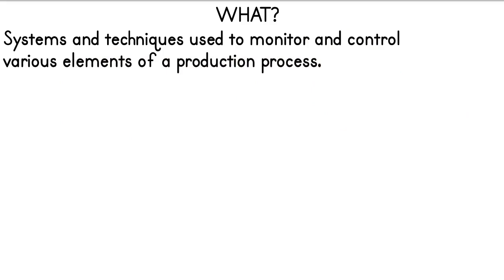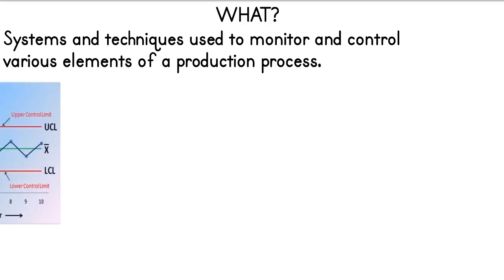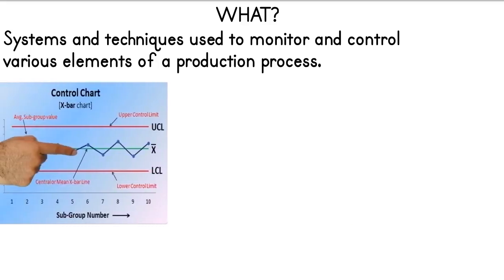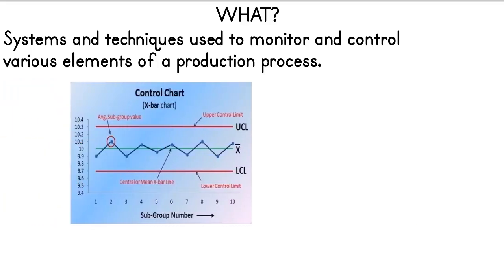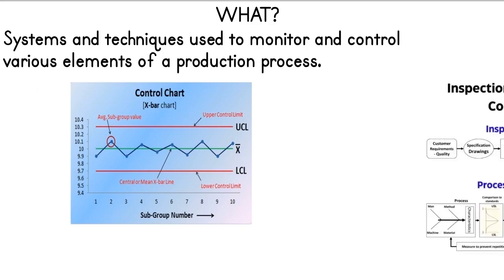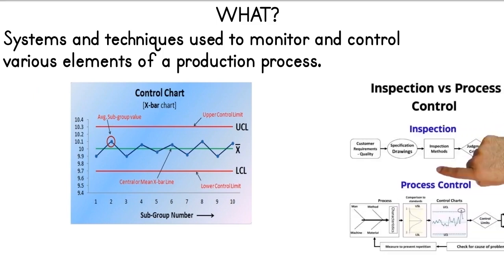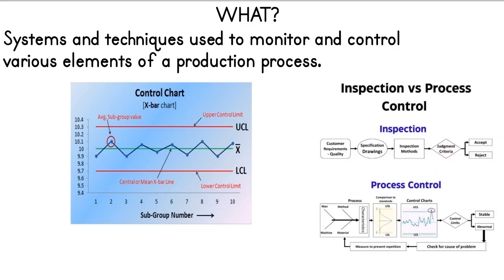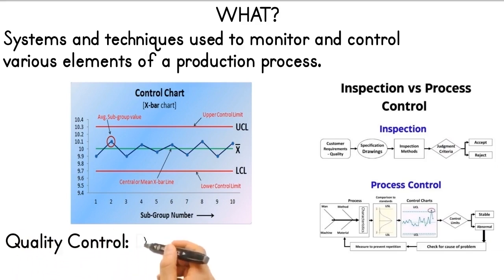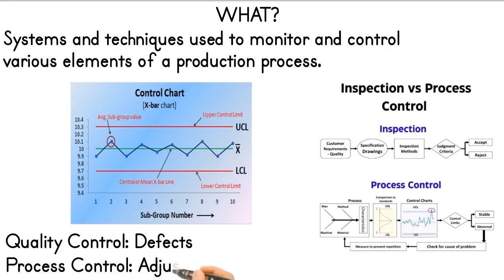Quality control. QC focuses on identifying defects in finished products through inspection, testing, and validation. This process ensures that products meet predefined standards or specifications. Process control. Process control is the practice of maintaining and adjusting various process parameters, e.g., temperature, pressure, speed, to ensure consistent production quality. It aims to reduce variability, maintain stability, and optimize efficiency within production processes.